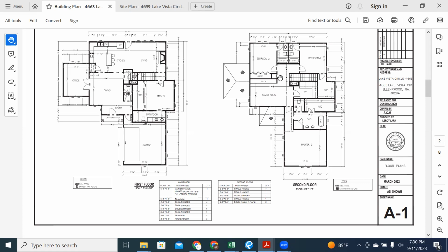Bedroom walls, some of this wall right here is shared by some of this wall. So he's basically looking at it as, okay, I'm bringing all this load from upstairs onto the walls down here. So I want to reinforce the foundation that this first floor walls are going to be framed on, so that the additional weight coming from these walls, it can support it. So it's best practice. Everybody doesn't do it.